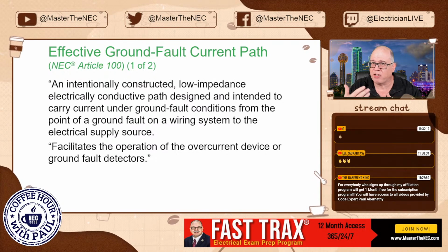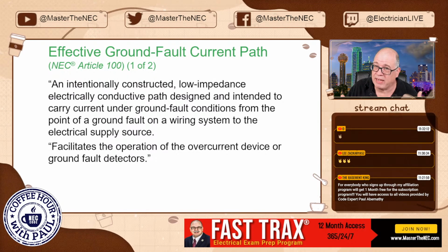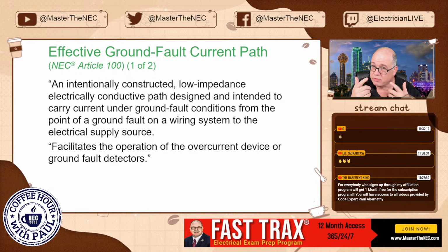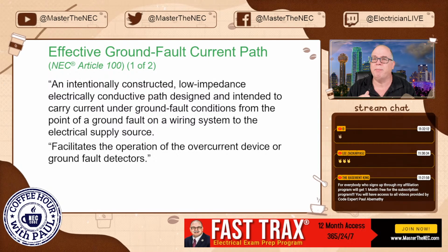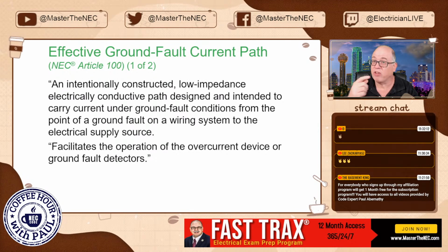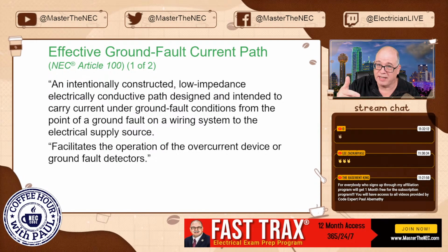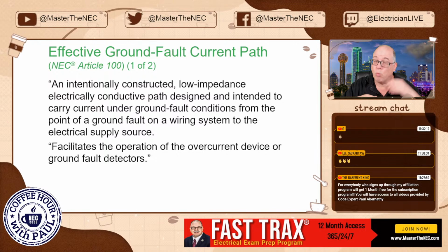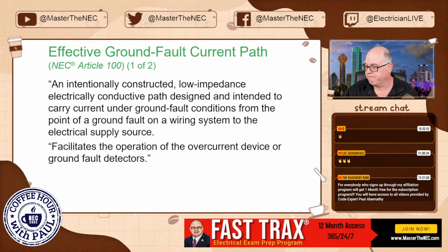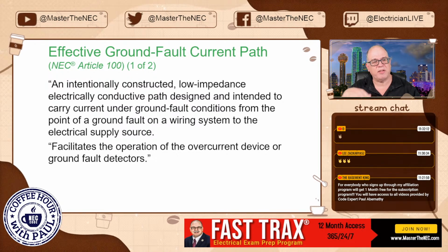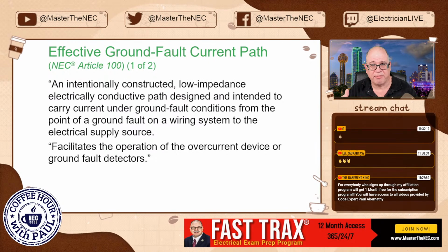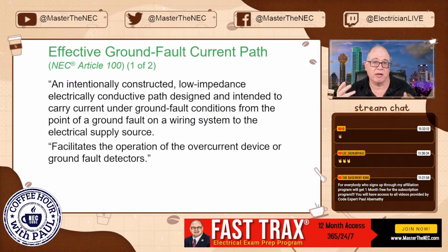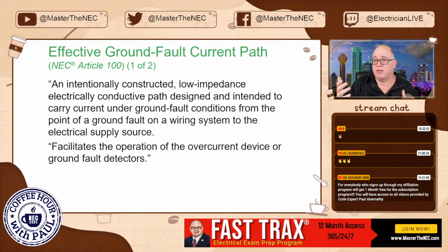That's why people in industrial facilities, and by the way, we have a course called Industrial Wiring. Check it out. It puts equipment in a safe position. But if there's another fault to another leg in the system, then it will trip the overcurrent device, okay? So an ungrounded system is designed, and it can be safe. Okay, you still have to have equipment grounding conductors. You still have to have those run through the system.